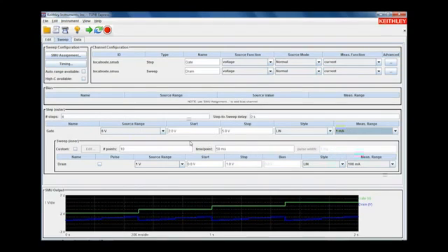We again have to go to the 6 volt range on the drain, as I want to sweep from 0 to 5 volts in 0.1 volt steps. So that'll yield 51 total points here. And the measurement range at 100 milliamps is correct because we will be setting a compliance limit of 50 milliamps, so that's appropriate here. Now let's hit the green run button, which is the arrow up at top here. We can set that, and it'll gray out until it's finished running.